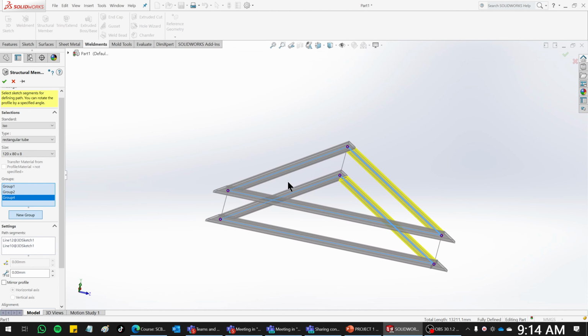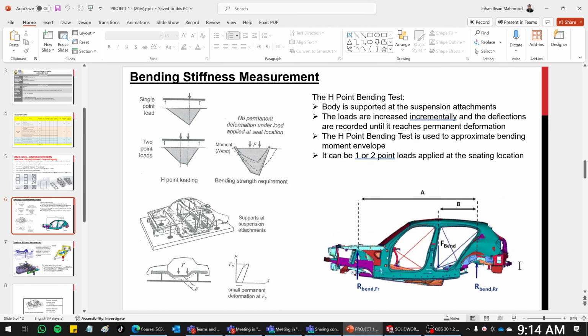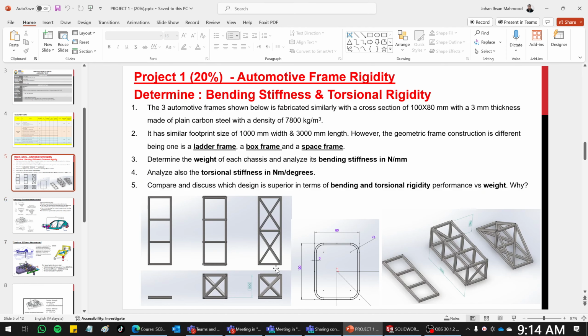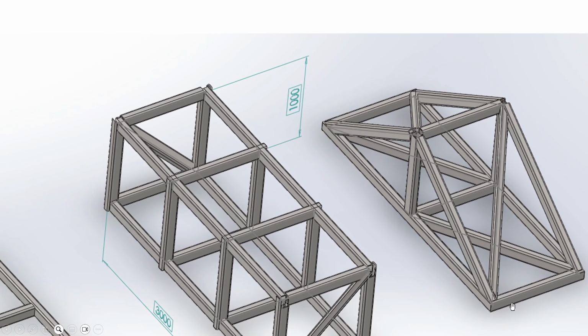Oh, currently everything is like that. Oh, that's why. You have to weld your things properly. If I look here, this model is actually welded at the bottom frames first. So if you weld the bottom framing first, then it will go up as it is.